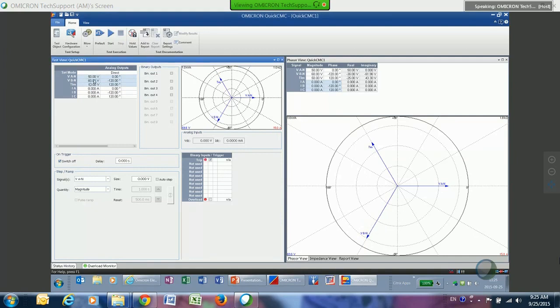And so now if I right-click on it and do equal magnitudes, it would change them all to 50 volts for me. So whichever cell I select or right-click in is the one that I would change to. So let's just say I wanted to make C 60 volts, that's fine. But if I wanted to do them all the same, click on phase B, do equal magnitudes, and it basically fills in the blanks for me.